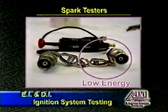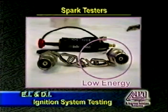Now on Ford multi-spark systems, beginning in 1990 on the 1.9 Ford Escorts, where we fire that spark plug 4 times, it will not like a dual ST125 spark test. Okay, so that system will bail out. If it is a 94 or later multi-spark Ford, they still will not like double stressing a coil pack with 2 ST125s. Our recommendation to you, if you want to stress a coil pack on a Ford or a Chrysler, use the 2 low energy clamped together.